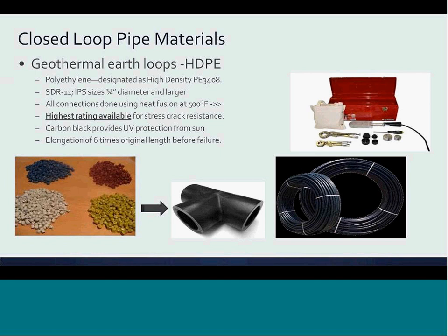The current industry material for ground loops in most states is plastic pipe, specifically high-density polyethylene pipe and cross-linked polyethylene, or PEX-A, pipe. While it isn't highly conductive, it is used due to its performance over time. When forming design calculations for the ground heat exchanger, good designers quickly realized that the greatest resistance to the heat transfer process is the earth itself. Installing highly conductive pipe will not significantly improve the ground loop performance.